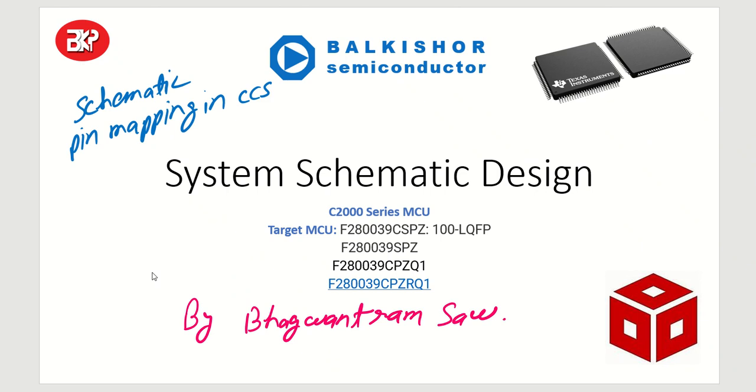Namaskar, my dear friends. Let us design a C2000 series microcontroller system circuit. We are going to consider the F280039CSPZ device or the CPZQ1 device or the CPZRQ1 device. These two are the same device, just tape and reel. This will be a 100-pin LQFP package.